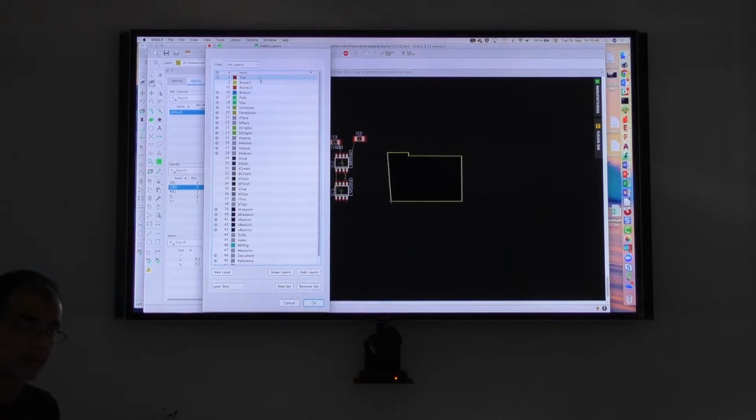In our setup, we used 4 layers. That's the reason why we have 1, 2, 15, 16 here. 1 and 16 is visible. Pads and vias. These are functional layers where we draw the pad and the via.